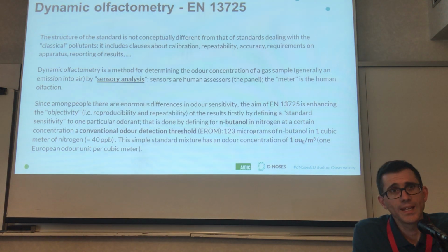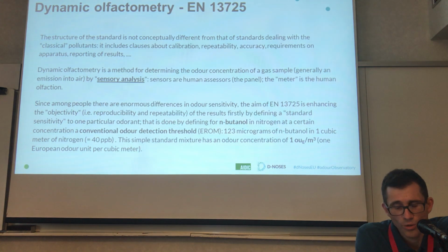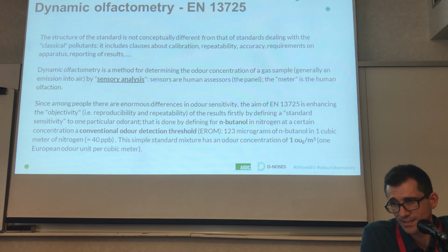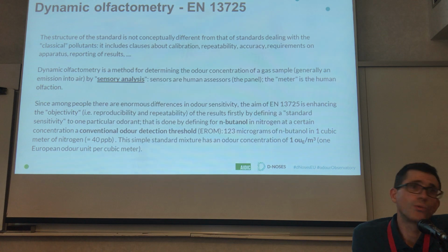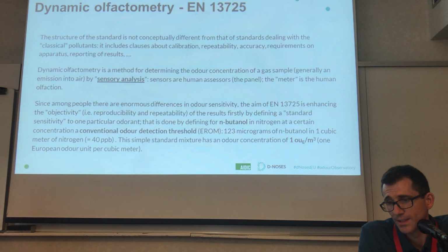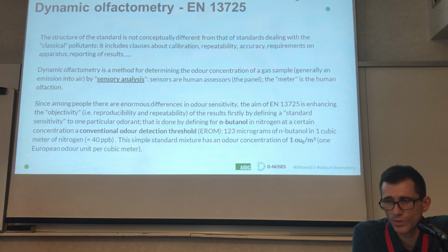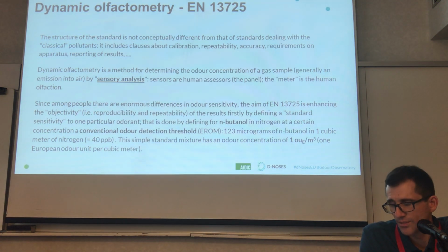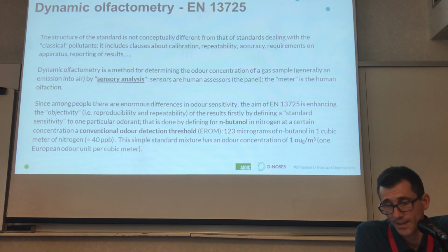So the main aim of the standard is enhancing the objectivity of the results by defining a standard sensitivity to one particular odorant. This particular odorant is N-butanol, and the standard defines the conventional odor detection threshold of N-butanol in nitrogen.